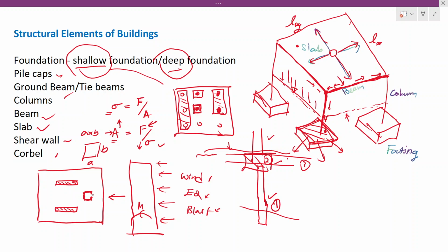So if you have a lateral load like this, these two walls will bear it. For example, in this lift, these two walls can carry the loads applied from this side. When you have a load from this side, this type of wall doesn't work, but this wall will work. So you have to have walls in this direction. We have to keep these walls symmetrically, then there won't be any torsional effect in the structure.